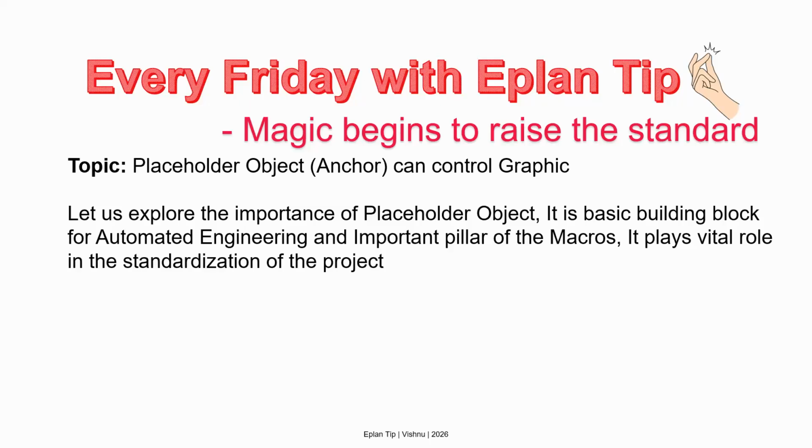Whether you create from the macro and drag it into the schematic and place it, or directly you make all the schemes and put the placeholder object directly in the scheme, that is also possible. But it makes more sense if you create a macro and put the placeholder object into that and start controlling those things. Then it becomes more important for us to get into that line of working. And if you're looking at standardization, definitely this plays a major role.